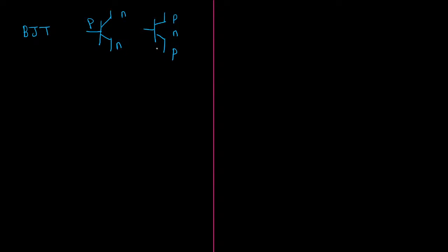If you take the transistor, we will have three terminals: collector, emitter, base. Through the emitter we are delivering the current, so the direction of the current will be outward in the NPN transistor. But if you focus on the PNP transistor, through the emitter we are injecting the current, so the direction of the current will be reverse. So this symbol might be very easy. Others are also easy, but you should try to remember.